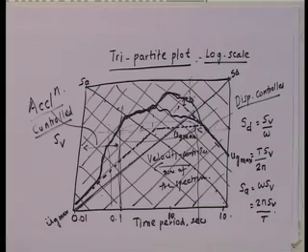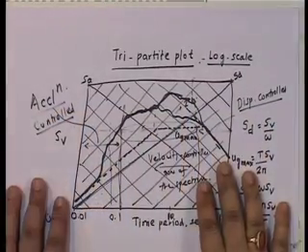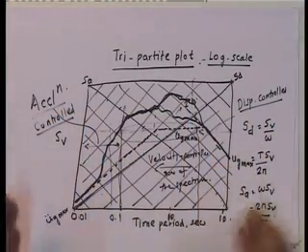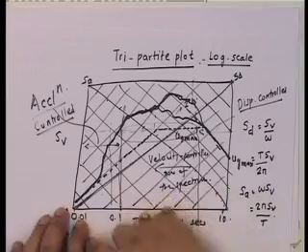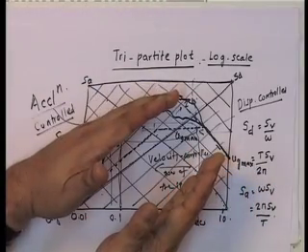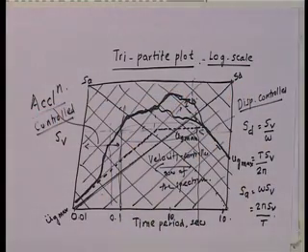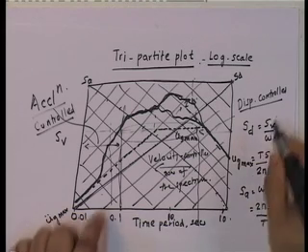Here what I have done is I have plotted the spectrum, all three spectrum. You can see, as I told you, you look at it this way, you see the acceleration spectrum. You look at it this way, you see the deformation spectrum. You look at it this way, you see the pseudo velocity spectrum. All three spectrums are on the same plot, basically because they are all related to each other.